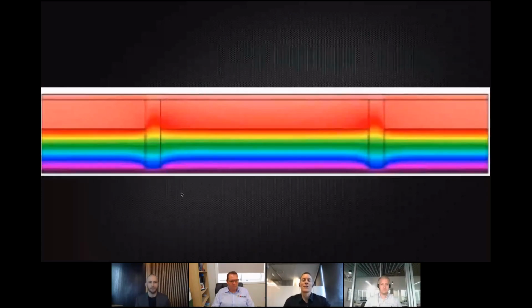It's totally related to the conductivity of the frame itself. And so the numbers, again, I'm going to repeat this. The timber has a conductivity, and our pine that we use generally has a conductivity of 0.12 watts per meter Kelvin, and fluffy insulation has 0.04. So that's about 3 times, and I know the data on the screen before said 4 times, but I'm calling this 3 times faster heat transfer through the timber frame itself. And it's shown here by the curving of those lines of the color into the timber.